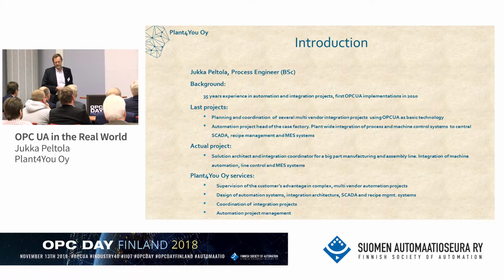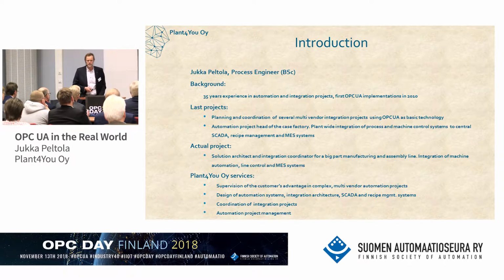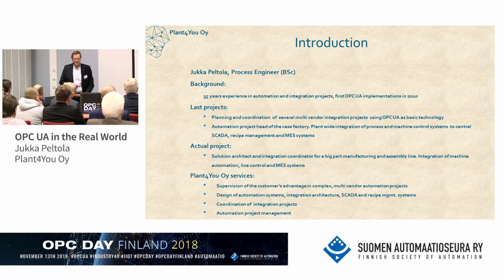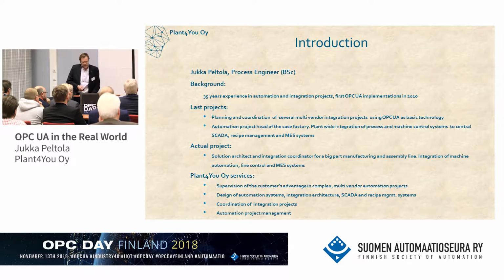Of course, for the first ones we had to use it, because at that moment there were no embedded OPC UA servers in the market for PLCs. So we used UA Gateway from automation, and Process was implementing these OPC UA clients for MES applications and SCADA applications. But now we can really use these basic methods and services of OPC UA.